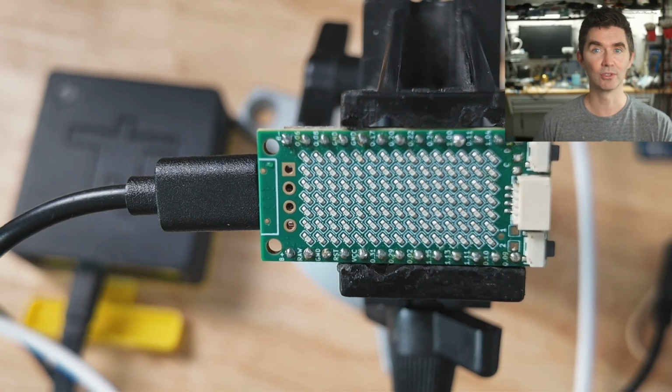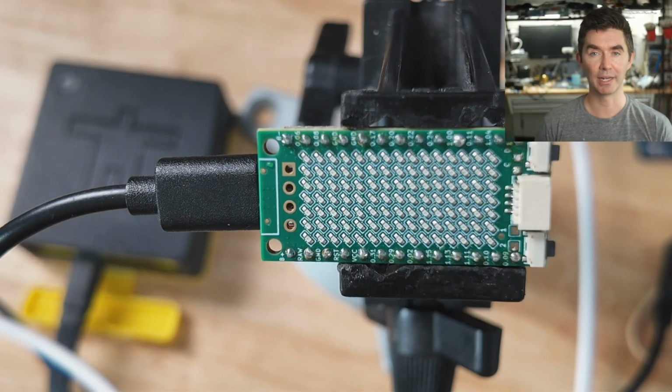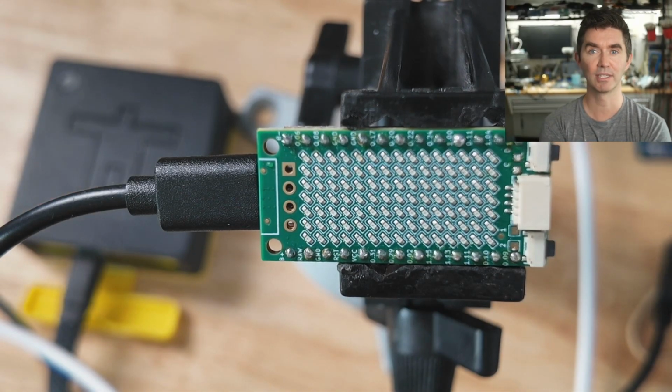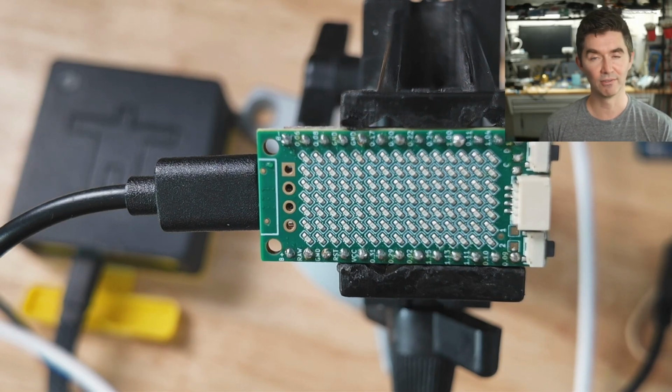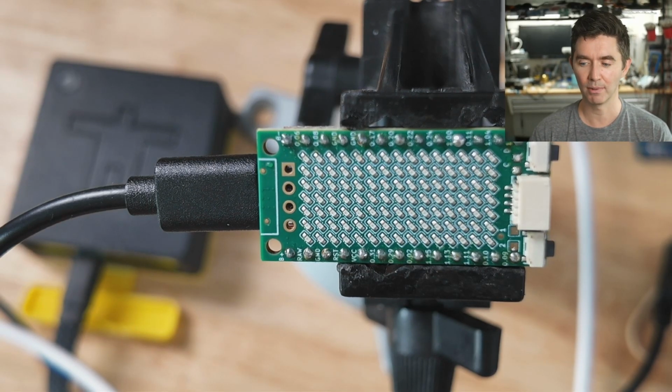But sometimes our users are approaching Goliath with an off-the-shelf device, like maybe this Thingy 91X in the back, or other commercially available development kits, and we want to get them started a little bit quicker, and they might not actually have a programmer on board. In fact, this device back here actually doesn't have a programmer. You need to have an external J-Link to talk to it, which is great. You don't want to load down every device with a programmer necessarily, but we still want to talk to the device itself, and so we want to talk to it potentially over serial. Again, lowering the barrier, making it easier for people to load this stuff up onto their devices. We want to do that with something like web serial.